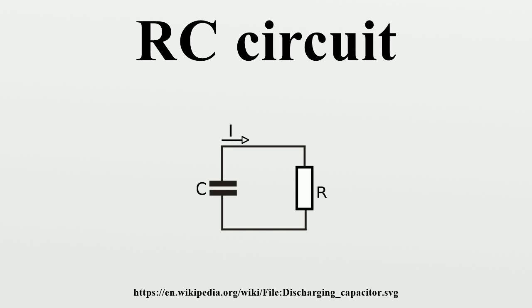Integrator. Consider the output across the capacitor at high frequency, i.e., this means that the capacitor has insufficient time to charge up and so its voltage is very small. Thus, the input voltage approximately equals the voltage across the resistor. To see this, consider the expression for the current given above. But note that the frequency condition described means that the resistor dominates, which is just Ohm's law. Now, the capacitor voltage follows the integral of the input, which is an integrator across the capacitor.